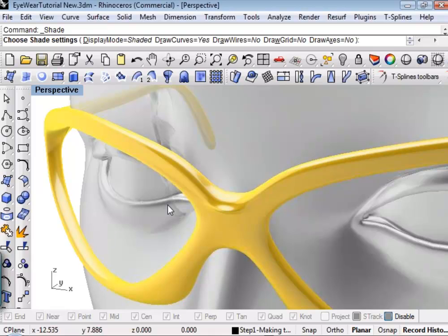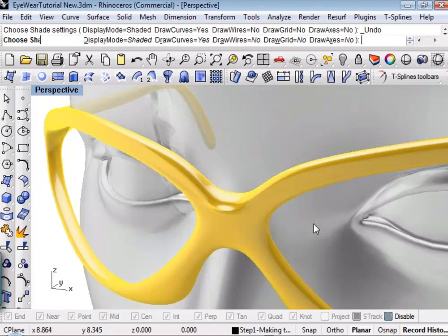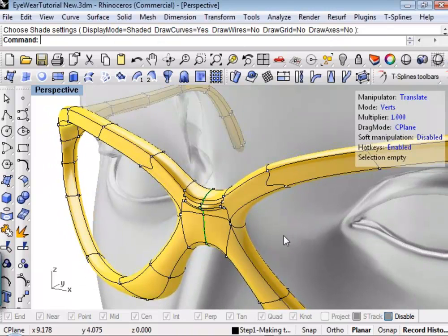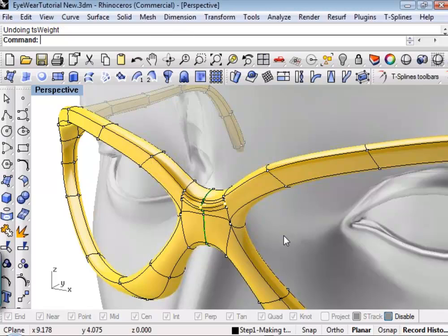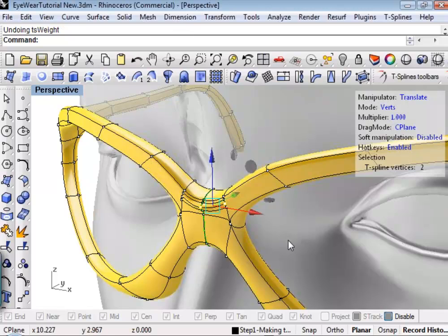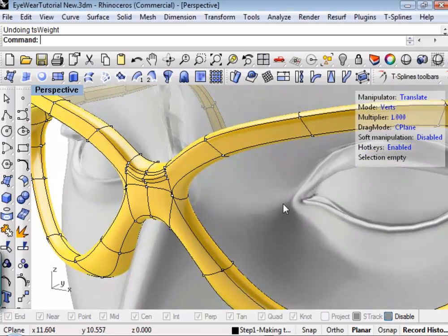The other thing about this is if you avoid knife blade kind of situations, your models are going to look better when they're rendered, because one of the biggest tells for something that's a CG model is edges without fillets on them. It just makes them look too crisp and too hard, and it's one of the things that make your models look CG. So I tend to like using weight, insert edge, and add weight and stuff like that in order to get nice soft edges, and then they render nice and they look more realistic actually.